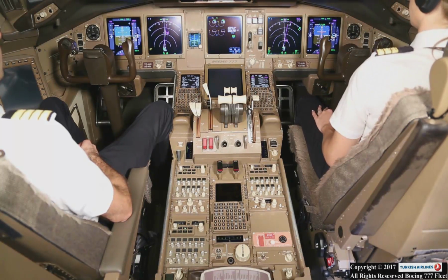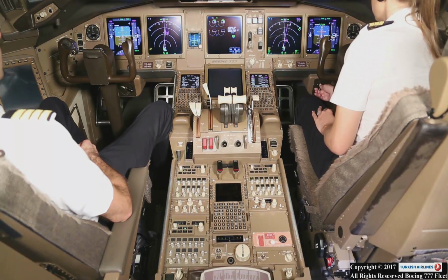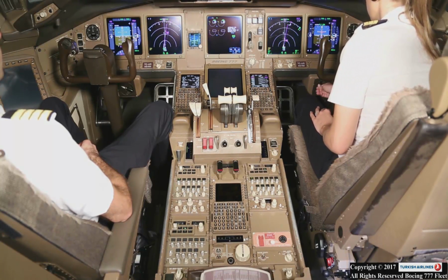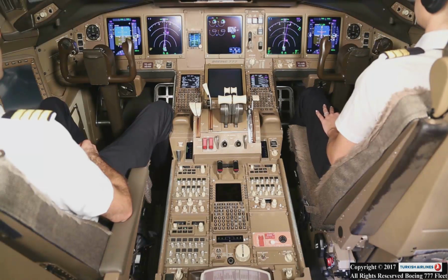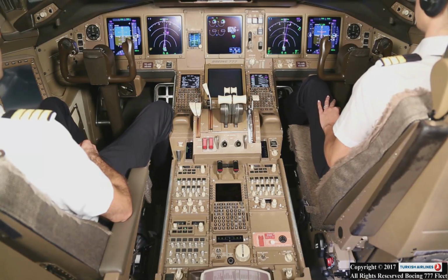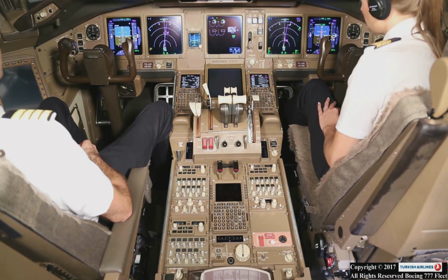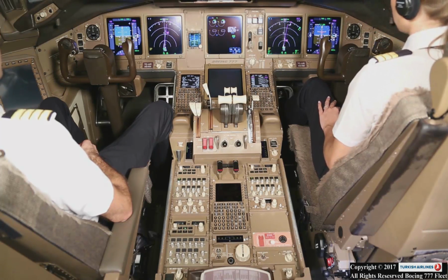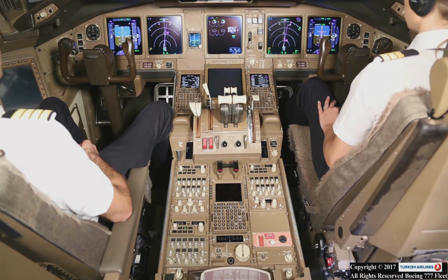Rudder pedals, adjust. Adjust the rudder pedals to allow full rudder pedal and brake pedal movement. Stow rudder pedal adjust crank. Warning: if the rudder pedal adjust crank is not stowed after use, rudder pedals may move out of the desired position. Seat belt and shoulder harness, adjust.